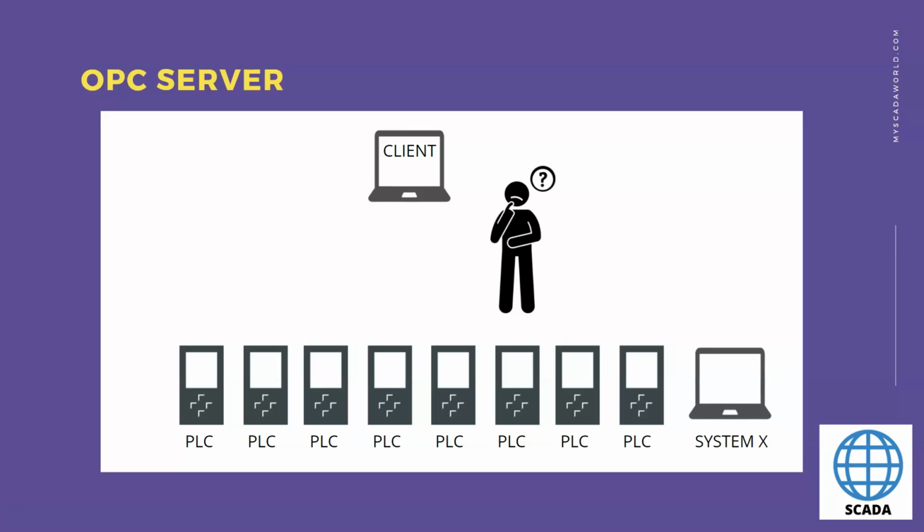It is the OPC server. OPC server is the basis of OPC communication. It's software that implements the OPC standard and provides the standardized OPC interface to the outside world. So we have one software with standardized communication to our PLCs and systems, and this gives the interface for the OPC clients to communicate with this server.